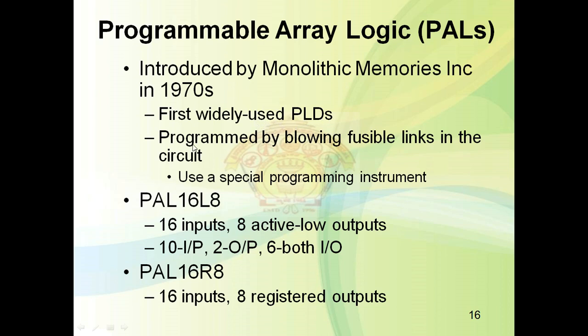It is programmed by blowing fusible links in the circuit. For that purpose, a programming instrument will be used to blow the fuse.